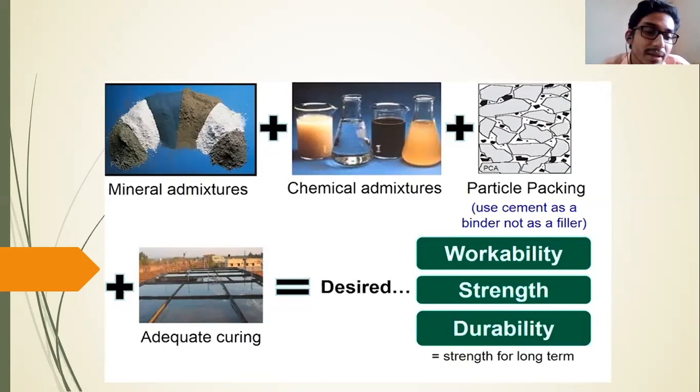You can see, again I am emphasizing one thing more and more: adequate curing. Adequate curing is a very, very important thing. If you have a very good material, very good mixing properties, and very good placing of concrete as well, but the curing is not good, you won't get the desired strength of the concrete, and within a very short time the concrete may start failing. I'm not going into detail on that. I hope you all know about the importance of curing.